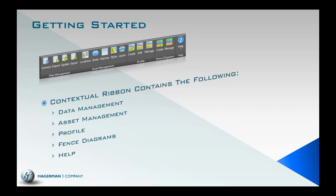We can have several, as many as we need to, and we'll see that again once we get to that part. Okay, we also have the ability to update our boreholes and access any changes in our database. If any of the files have been updated, as long as we keep the same name, we can go click update. It's going to go back, take a look at that information. It will actually show us in a dialog box what changes there are and what updates are going to occur. We can also export. That one's pretty straightforward. We can export our information out to an external file.